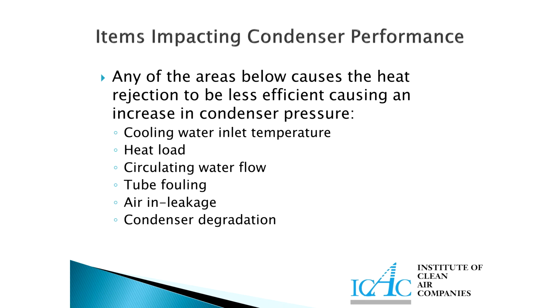The heat load, how much heat is in there. Circulating water flow is another one. If you have fouling inside the tubes, or if you have some tubes that have gone bad and you plug them up so you don't have any leaks or anything like that, that impacts it.